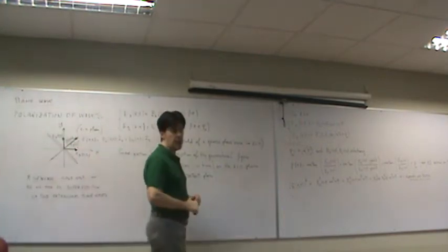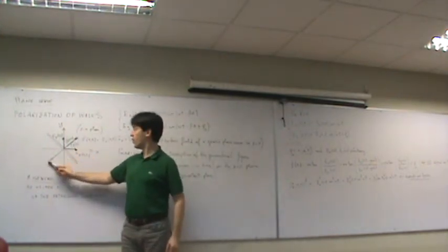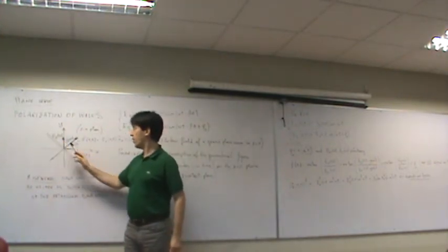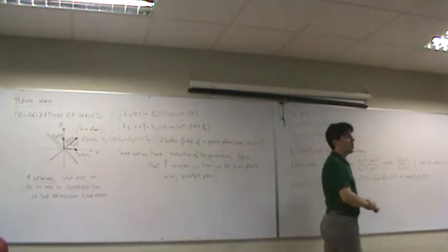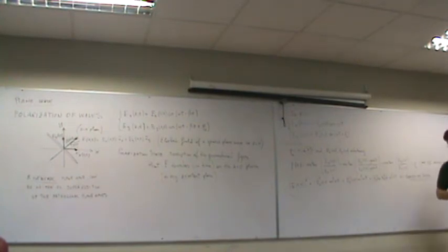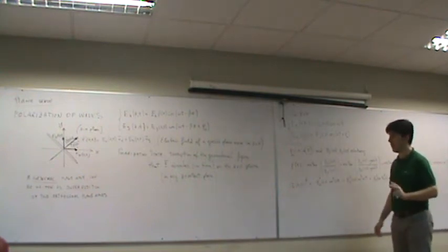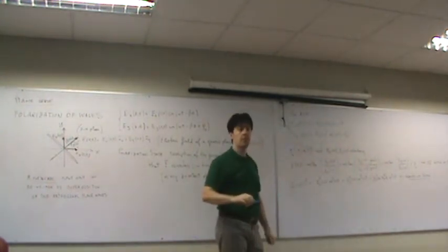Always a linear polarization, but instead of being in the first and third quadrant, it will be in the second and fourth quadrant. So there is nothing fascinating. Linear polarization is important because a lot of applications, that is a lot of antennas, use linear polarization. Not all of them, most of them. Questions before I wipe up?